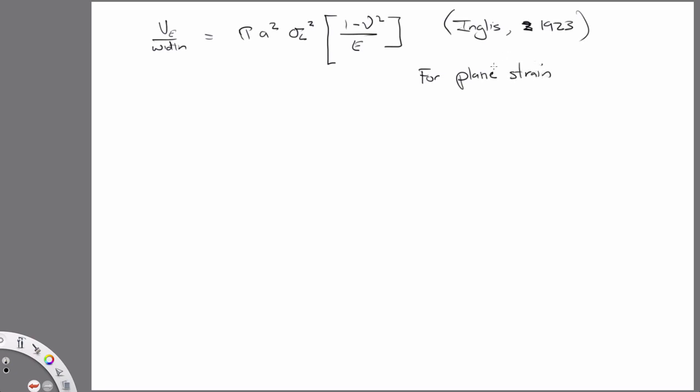So we haven't really talked about plane elasticity in this course, but sometimes, under certain scenarios, you can simplify the full 3D elastic equations to 2D, one of them being plane strain. So plane strain is actually the scenario for which we derived equations for stress on an earlier homework assignment. But this is the idea that the body is so thick in one direction that the strain is essentially zero in that direction, right?